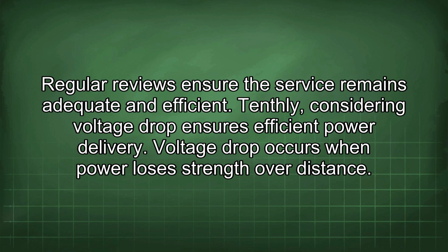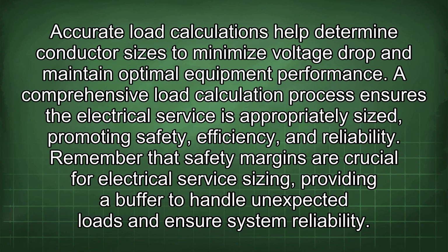Tenthly, considering voltage drop ensures efficient power delivery. Voltage drop occurs when power loses strength over distance. Accurate load calculations help determine conductor sizes to minimize voltage drop and maintain optimal equipment performance. A comprehensive load calculation process ensures the electrical service is appropriately sized, promoting safety, efficiency, and reliability.